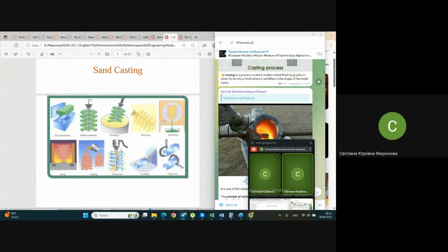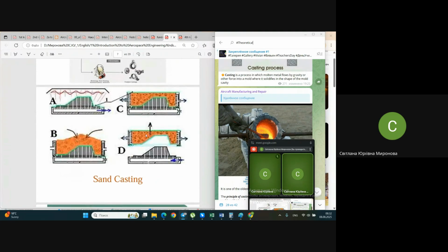The shape, this mock-up, this standard of the part to be produced, will already not be solid. It will be made of easy meltable material. Typically, it's wax, paraffin, something like this. Also, it may be some other easy meltable material, for instance, plumbum, maybe.